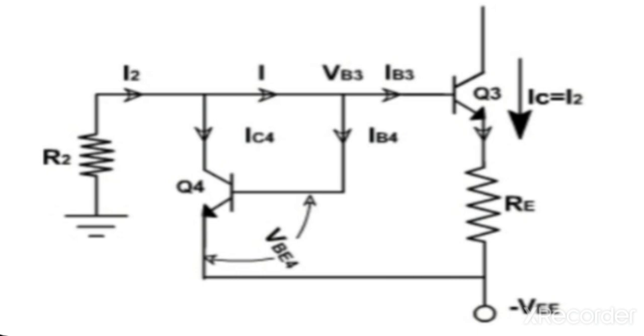In this circuit, transistors Q3 and Q4 are identical. Hence, their base emitter voltages must be same and also their base and collector currents must also be approximately equal. Hence, VBE3 is equal to VBE4 and IC3 is equal to IC4. Also, IB3 is equal to IB4.